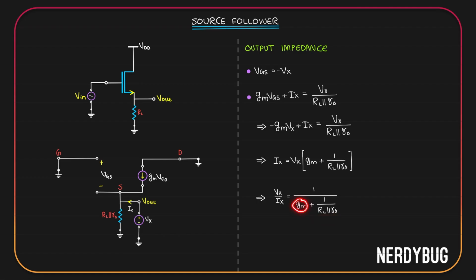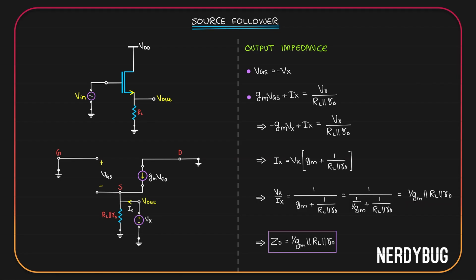We have gm here. I am going to write it as 1 divided by 1/gm. Imagine this is R1 and this is R2. What I am taking is the reciprocal of 1 by R1 plus 1 by R2, which basically means I have a parallel connection of R1 and R2. If we apply that idea over here, this is technically the equivalent resistance of a parallel connection of 1/gm and RL parallel to R0. Vx by Ix is 1/gm parallel to RL parallel to R0. And that is our output impedance.